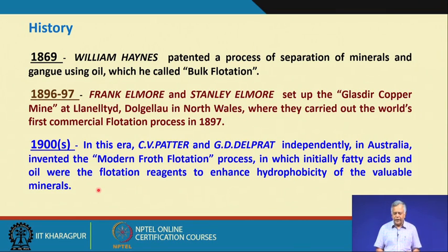Before we get into the next slide, let me explain, otherwise you may be distracted, what happens when you have very fine particle size ranges. Why should you have very fine particle size ranges? As the grade of the ores deteriorates over time, it demands that the liberation size becomes finer and finer.